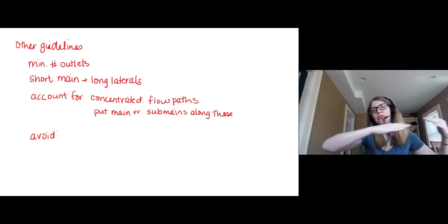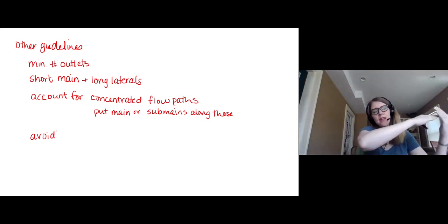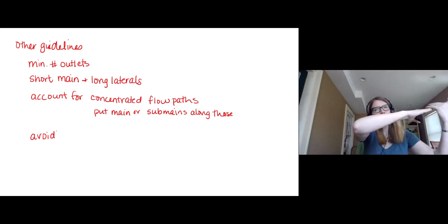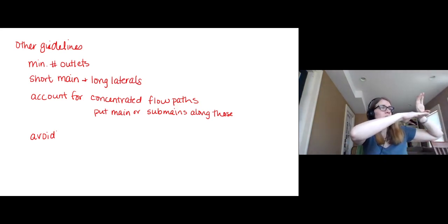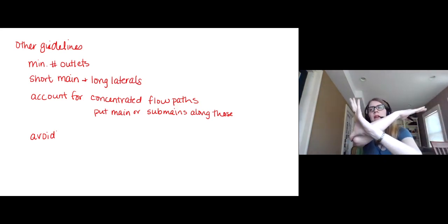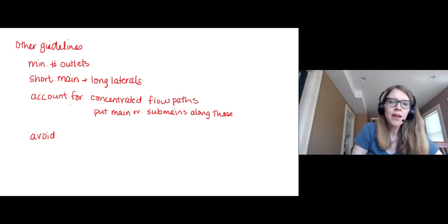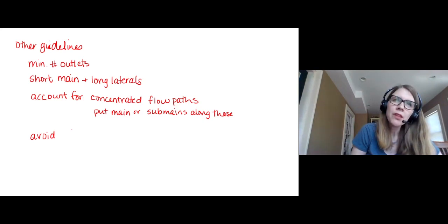It could mean that if you're draining a large area with the same line, in order for you to put a little bit of slope on there, you're going to end up being shallow in depth at the top end and deep in depth at the bottom end. So you're going to have to kind of play with that to make sure that you're not putting any of that tile line super deep.